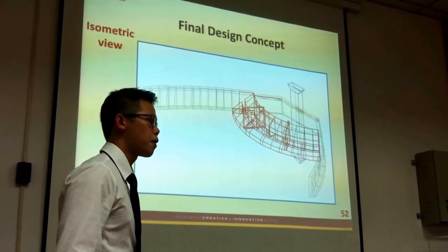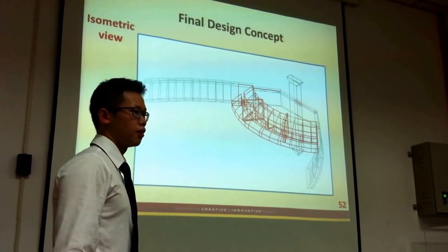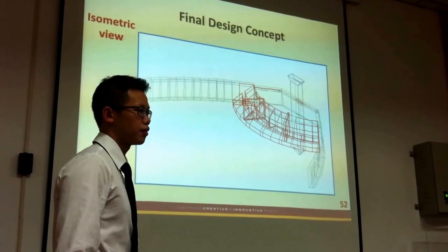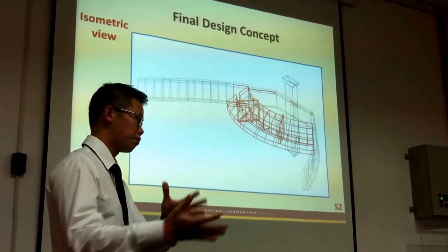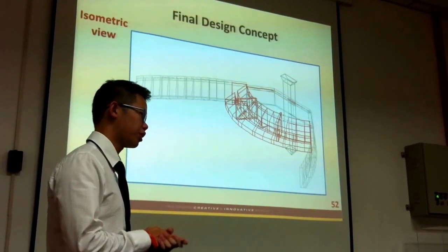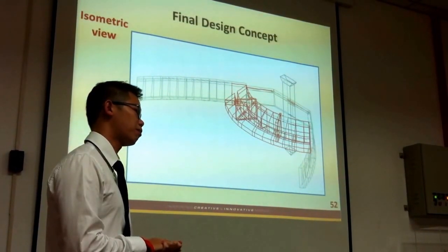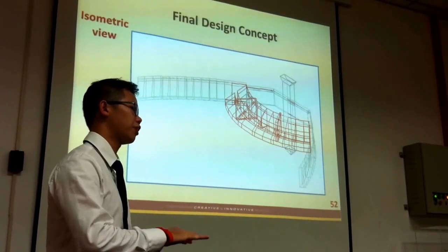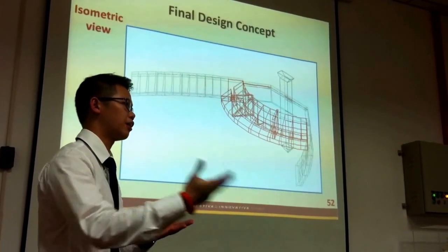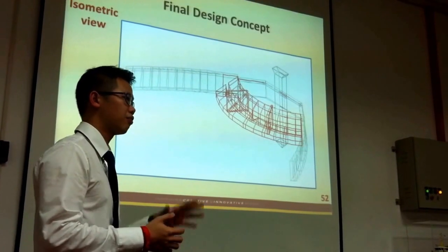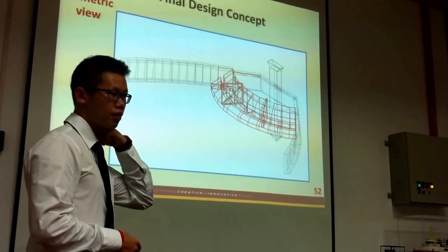So in the design you have two reservoirs? Two reservoirs. So the first 1 meter reservoir will be a different type. Basically, I haven't really done any design for the internal part because I was told to focus on this ramp energy collection area, to determine which ramp angle will yield the highest overtopping rate, so that in future work they can use this best ramp angle. So they'll incorporate my ramp angle design into their design.